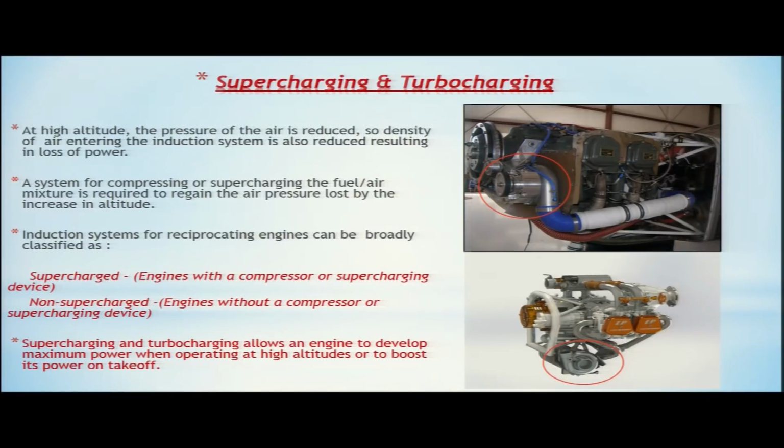When these engines fly up, there will be a reduction in power. Whereas supercharged engines have the provision to compress the fuel air mixture, so they will not face the problem of loss of power as they go up. So, two types of engines: supercharged engines and non-supercharged or normally aspirated engines.